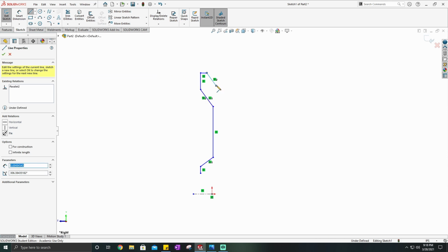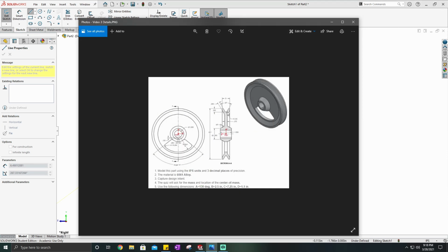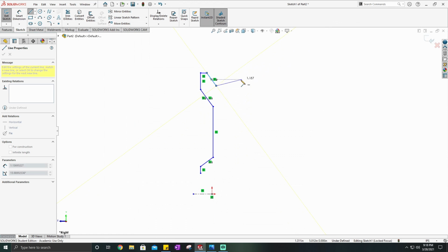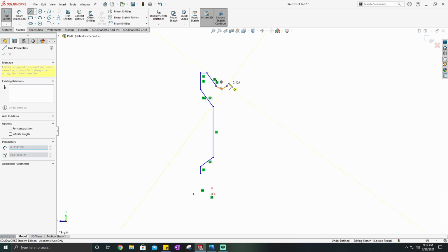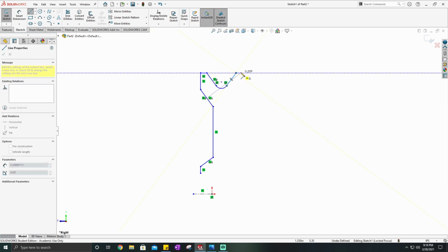And then a little tip here is, I know that this has a curve at the bottom of this. If I go back here, you can see that there's actually a little radius right here, as mentioned in the dimensions. And so in order to do that, rather than escape out of the line tool, select a circle tool, make it, trim stuff, and then put another line after, SolidWorks is actually integrated in to where if I am outside of my straight line and I go back onto the point, you'll notice that little circular yellow icon right there looks like a circle, and that allows me to create an arc. So then I'm just going to go ahead and place an arc, and then it goes back to the line tool, and I can continue placing my lines.